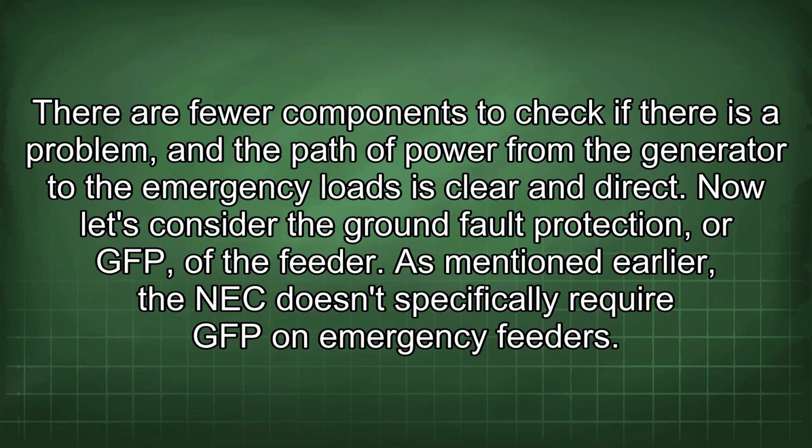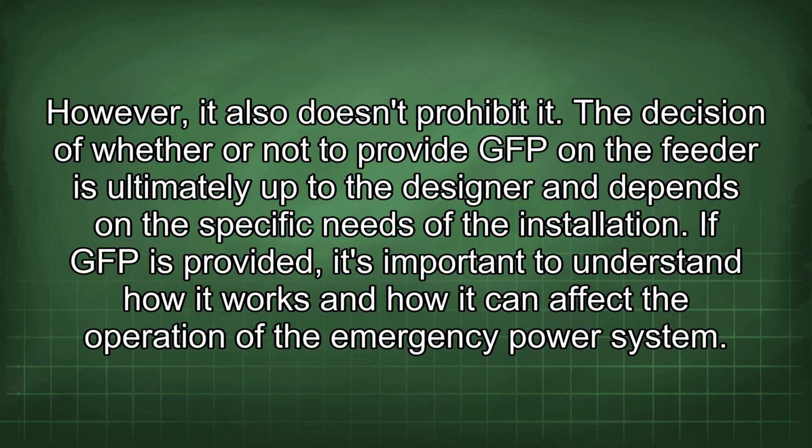Now let's consider the ground fault protection, or GFP, of the feeder. As mentioned earlier, the NEC doesn't specifically require GFP on emergency feeders. However, it also doesn't prohibit it. The decision of whether or not to provide GFP on the feeder is ultimately up to the designer and depends on the specific needs of the installation.